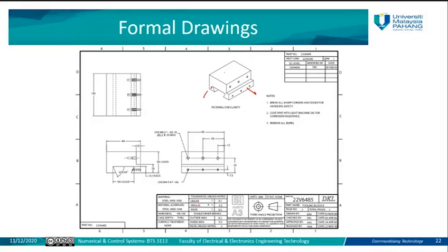The angles, what is the angle here, what are the tolerance values for the angle, for the line, for the rate, and so on. What is the type of the object projection here? Is it first angle projection or third angle projection, and so on? What is the revision date, and so on. All this information is available in one drawing.